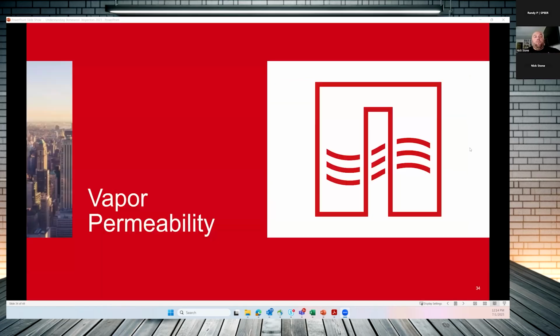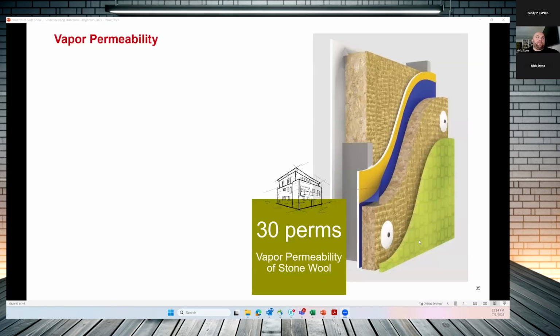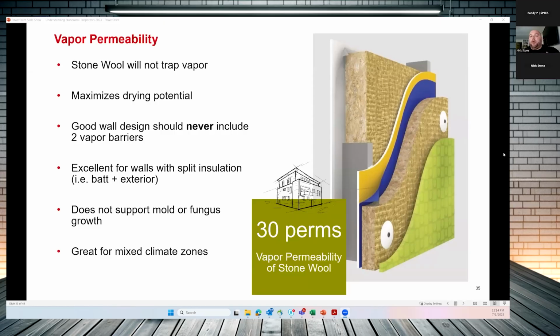Alrighty. So now we're going to move into a little bit more of the vapor permeability and the building science part of the business, the AIA. So starting off, what is a good vapor open wall assembly? Now, this picture here, unfortunately, is a northern picture. If you see the class one or class two vapor barrier here on the inside, picture that being gone. This is not something you're going to want to use in zone one, two, or three. Your vapor control does happen on the outside part of your sheathing. So please pretend that doesn't exist there.